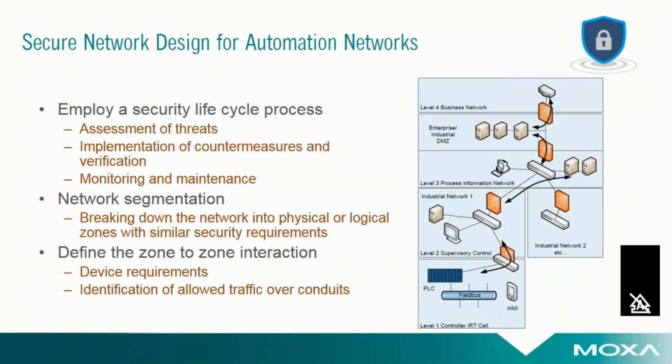So jumping back to the standard, now that we've discussed some of the device level concerns, let's look at the next part of this, the system level. So central to all cybersecurity standards is the need for a security lifecycle and process. This is a continual assessment of threats and system design. But cybersecurity also involves the segmentation of network architecture into logical zones of devices with similar security requirements. Communication between zones must be over a network link, which was referred to as a conduit. The interfaces of the conduit are typically terminated by a firewall device, which defines the zone-to-zone interaction. Only specific traffic is allowed to flow across these boundaries.